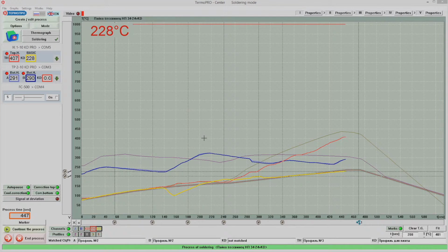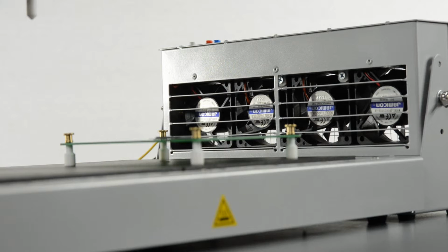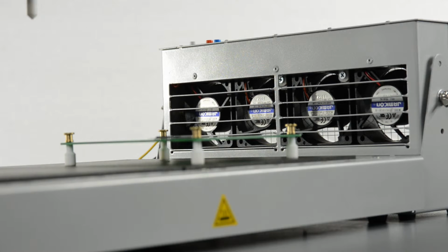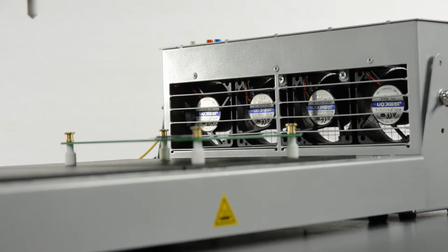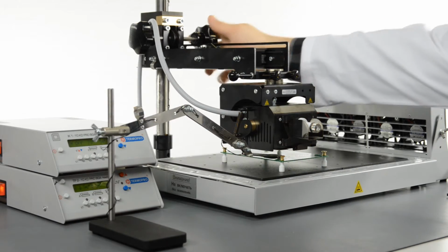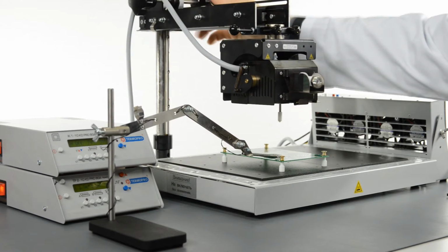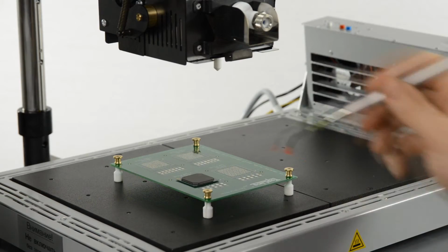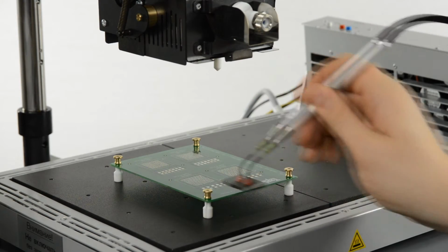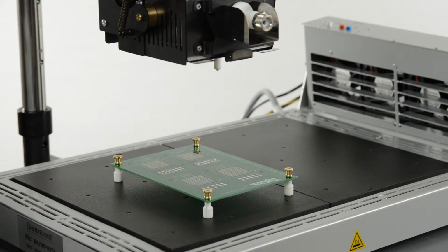Once the solder melting point is reached and the formation of contacts is completed, the program informs about the process completion. In case forced ventilation is required, the air cooler unit FC500 can be engaged at this stage, and the program will recommend the operator to raise the top heater from the working zone. The process can be stopped at any stage by pressing the End Process button. If you run component desoldering, remove the component from the board at this stage by the method adopted at your enterprise.